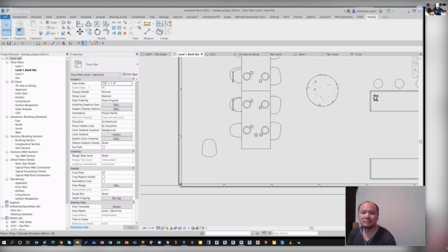It still has a host because it's in Revit. Everything has a host, right? So what you're doing is saying, I want you to mask at this level. You're almost controlling the bring to front or send to back setup, like you would with a detail region or anything like that. You're almost controlling the layers of that. And so I think that's actually what happened with your legs, probably that reference plane that you used, right?